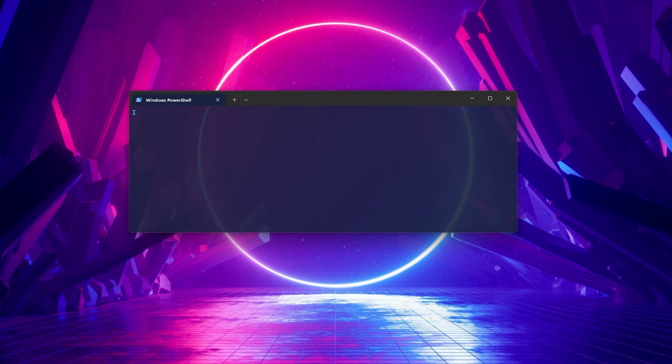you can imagine. Isaac Lab sits on top of Isaac Sim. It provides ready-to-use robotics environments, tools, controllers, reinforcement learning integrations, sensors, and robot models. Instead of building everything from scratch, Isaac Lab gives you a complete API for quickly creating robots, simulations, and learning environments. Together, they form an incredibly powerful platform. Even complete robotic stacks could be built in the simulation before ever touching a real robot. And Isaac Sim is a big reason why that's possible.